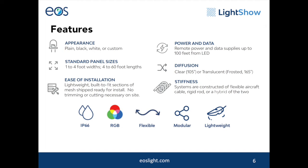The maximum distance between a LightShow panel and its drivers is 100 feet. The maximum distance between a LightShow Max panel and its drivers is 200 feet. For diffusion, the LED can be specified with either clear or translucent lenses. For applications requiring better off-axis visibility, translucent lenses should be considered.